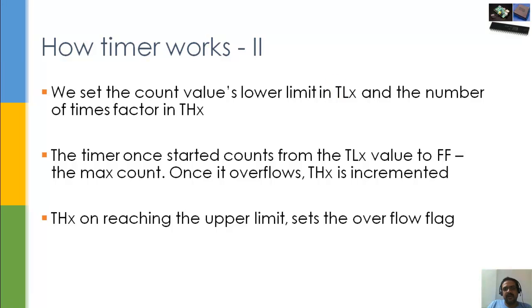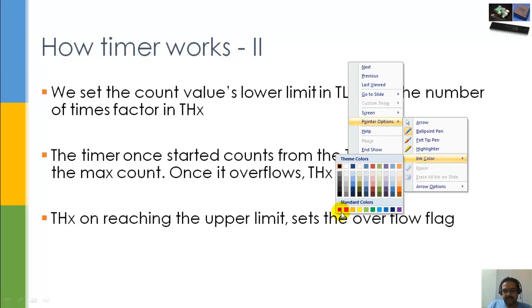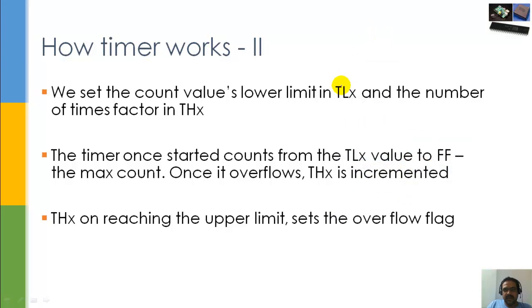For example, if I load FF in TL register, the timer will start counting from 0 to FF.